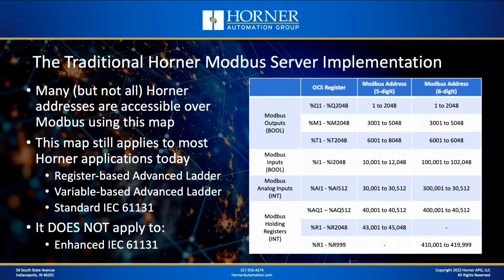3 of the 4 available logic languages in Cscape still use this map. If you're using advanced ladder, either register-based or variable-based, they still use this map. If you're using standard IEC, it still uses this map. And even though standard IEC and variable-based advanced ladder aren't purely register-based, in other words, you don't have to register map every single variable, the way they're implemented still allows this map to be used. However, this map does not apply to Enhanced IEC, and we'll show you why in the next couple of slides.